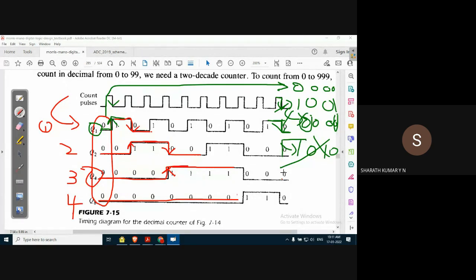We need to stop this. Okay. So initially, what is the condition of Q2? 0. So initial condition is 0. Let us note this. Okay. So what we want at the Q2 flip flop input is that it should remain 0, so that if the previous output goes from 1 to 0, the output of the third flip flop will go from 0 to 1.